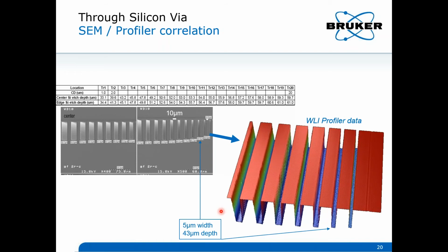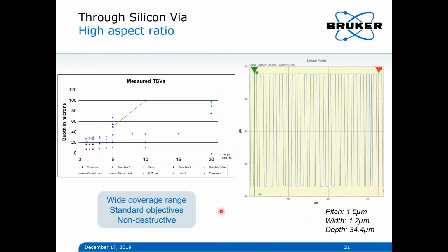So we can get accurate measurements of trenches, notably if you're using BOSCH processes for high power electronics, or to use TSV in order to have interconnects between dies.